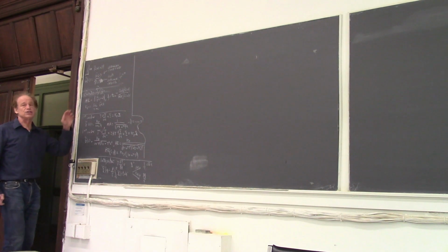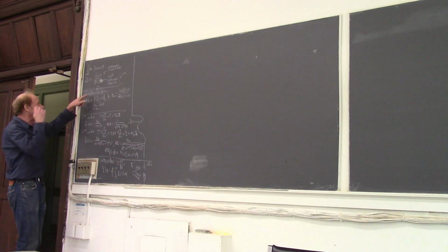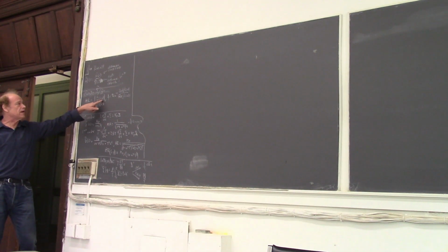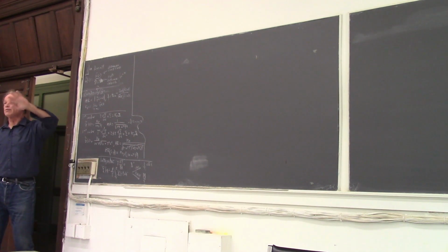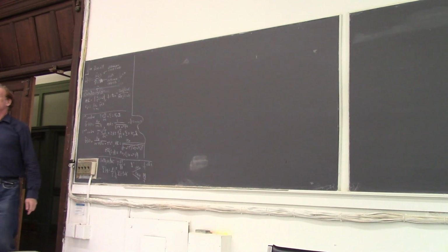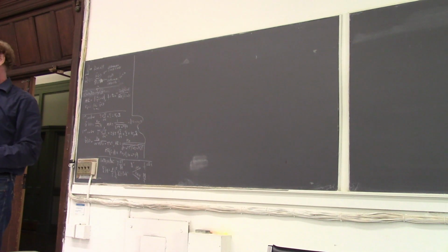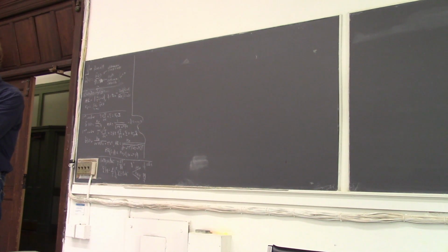And the amplitude ratio, we can get directly from G tilde without even doing the inversion. We saw that if we just take G tilde evaluated at omega, where omega is the frequency of the oscillatory input, and take the magnitude, we get the amplitude ratio. And phi, the phase lag, that is, if something's oscillating in the input, the output may not start oscillating until here, and that difference, that distance in radians, is the phase lag.